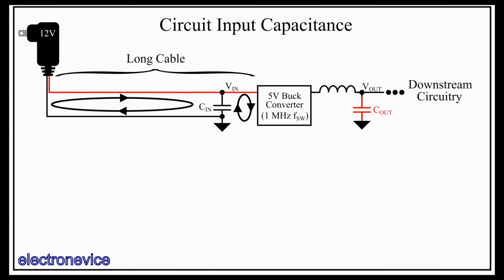The larger these two capacitances are, the better the reduction in electromagnetic interference, and the lower the voltage ripple due to the switching on the input and output rails. There are some trade-offs to making these capacitances too high, but that is beyond the scope of this video. Suffice it to say, having significant input and output capacitance is generally beneficial to the EMI environment and smooth operation of power circuits, and so we have to implement soft start circuitry to accommodate these capacitances at power-up.